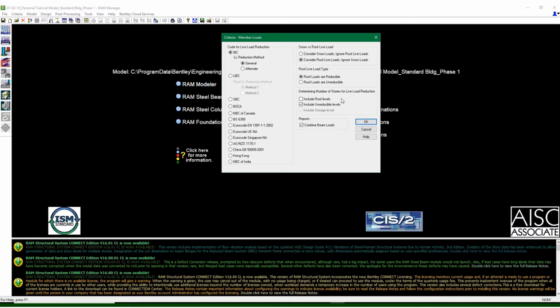And we could go into the discussion of this, but basically, the general idea is, do you expect the building to be fully occupied while there is also the maximum load or the design load applied to the roof? And just in general, again, I'm not going to take any live load reductions in this case. It's a one-story building, simple, and I want to be able to easily track the loading.